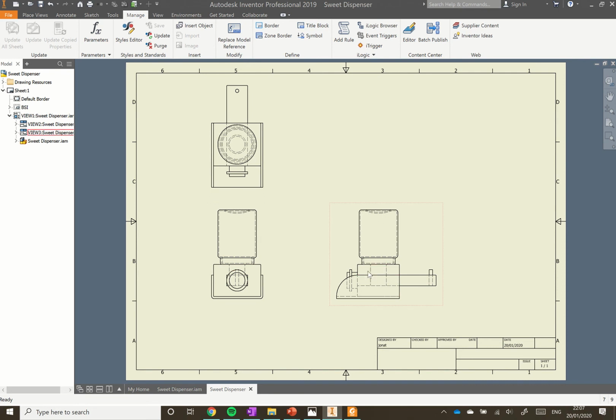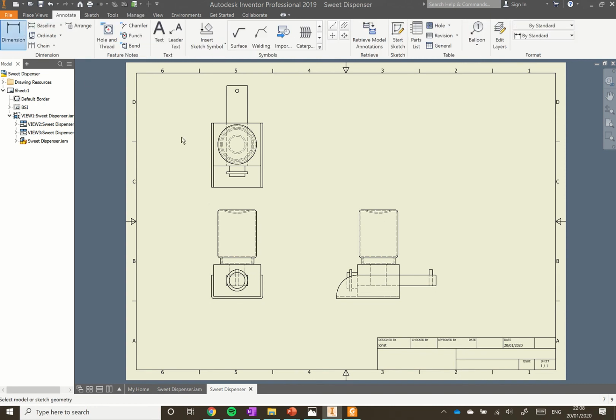You can see the cutting that goes through into that middle layer there, and we can also see the position of the hole in the drawer, as well as where the stopper goes into the drawer, including the detail of the jar. So way more information there. That's really useful when you want to convey more information to those who are looking at the drawing. So now we can go up to annotate, go to dimension, and we can add some dimensions.